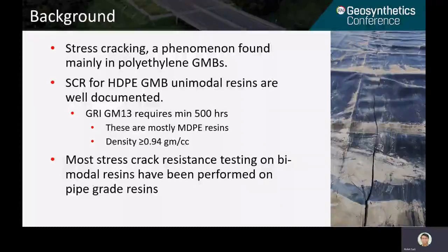Now, these are the properties that are performance indicators for high performance piping. These tests cannot be extended as is to geomembrane applications, just because it's a different product type, a different end use application, and also the biggest thing is manufacturing. You have to look at the equipment capabilities to see whether that type of resin will be able to extrude through the equipment the geomembrane companies have right now. So we needed to devise our own methods to evaluate the geomembrane performance.